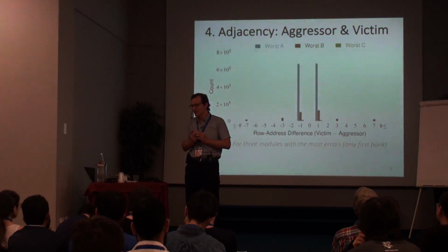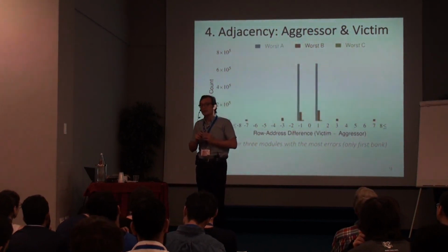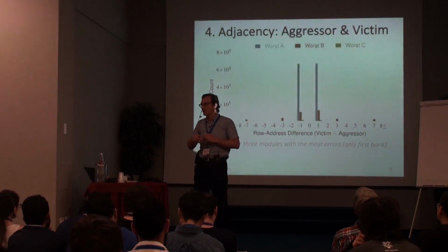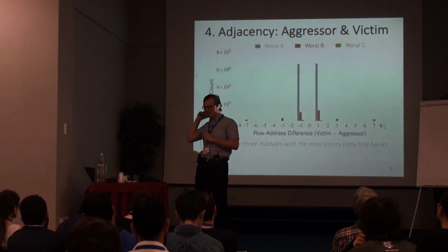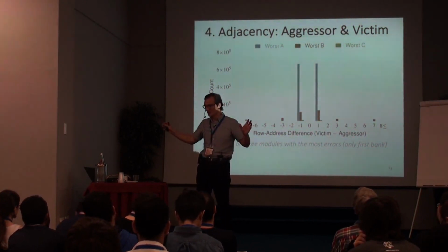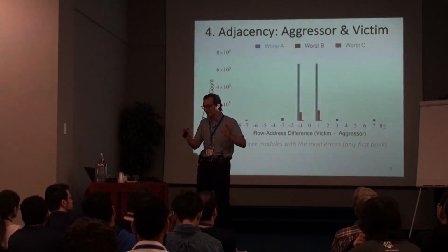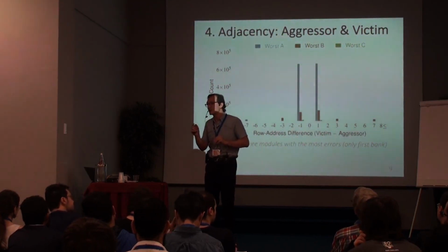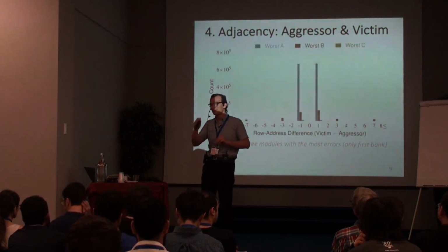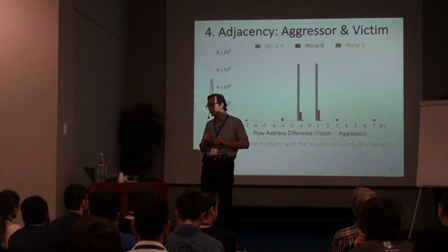But doesn't FTL kind of... Yes, FTL tries to minimize those errors. You add error correction, you add signal processing, and that's what that paper is about, the error characterization paper. If you're really interested in that, you should read that long survey paper. That's the result of 8 years of research. But it doesn't fundamentally change the fact that you get more errors. It corrects as much as possible, but you get fundamentally much lower endurance to begin with for a triple level cell, for example.